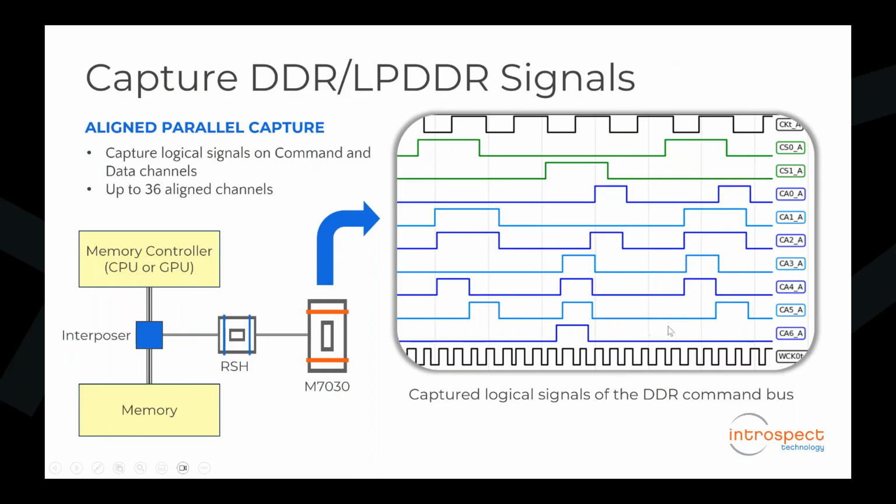So fundamentally, at the lowest level, the protocol analyzer is essentially a logic analyzer. It will just detect edges and display them and give you the exact timing at which they appear. So if there's any timing mismatch, like where my mouse is pointing here, you would actually see it. So that's fundamentally what the protocol analyzer is.